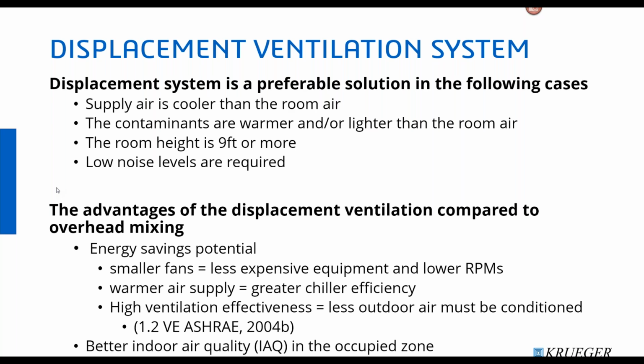Also, low noise levels. So displacement, we're discharging at a lower velocity. So the noise levels coming out of displacement devices are typically in between 20 to 25 NC. So this is one of the reasons that schools are very, very interested in the displacement applications. A lot of the orders that we see are specifically for schools.